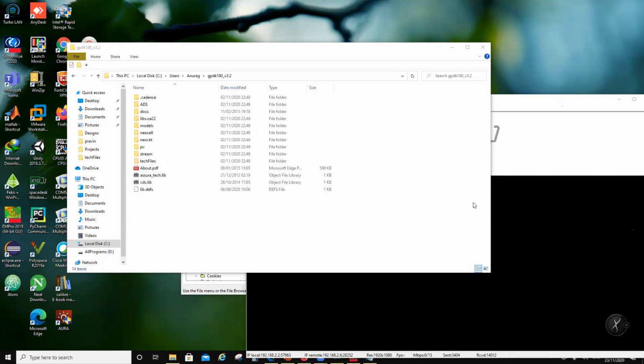If the thing becomes large, like multiple wavelengths, then you use FDTD. And discretization in FDTD is also now not one uniform cell size. You can have different size cuboidal cells, and you can move from one mesh to another.